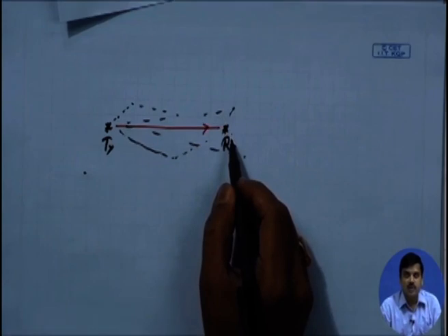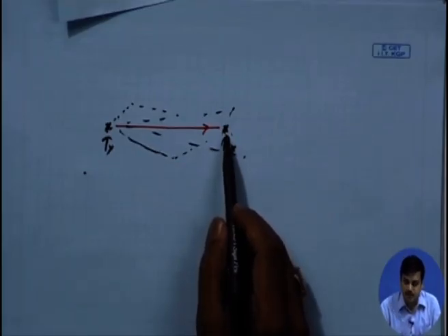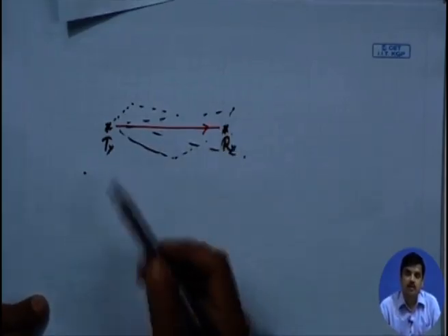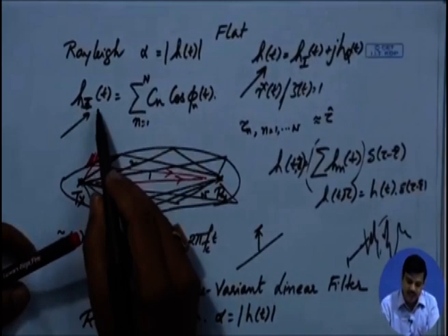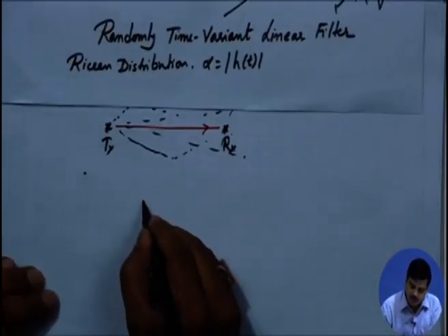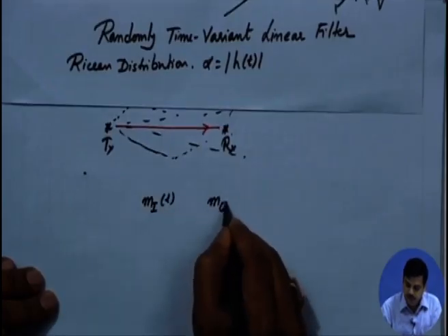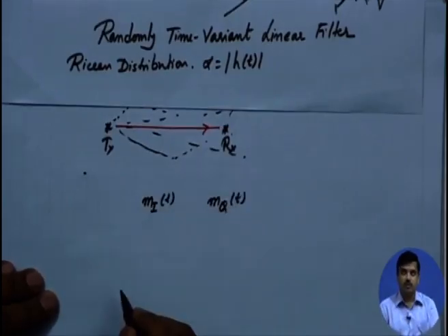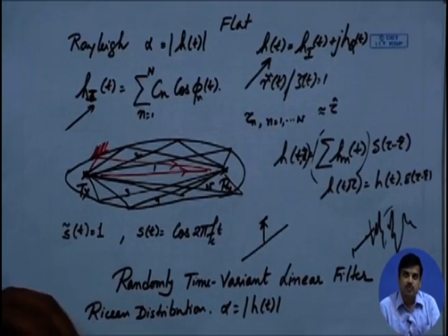So, we said last time you could almost imagine this to be an AWGN condition, if there is only additive white Gaussian noise, or near to ideal condition with a signal strength. Under these conditions, earlier we said that Hi is 0 mean, Hq is 0 mean, but in this case Hi is not 0 mean, but there is a certain Mi, a mean associated with the I component, and a mean associated with the Q component. So, what we see is that there are two different kinds of very prominent distributions that usually would appear.